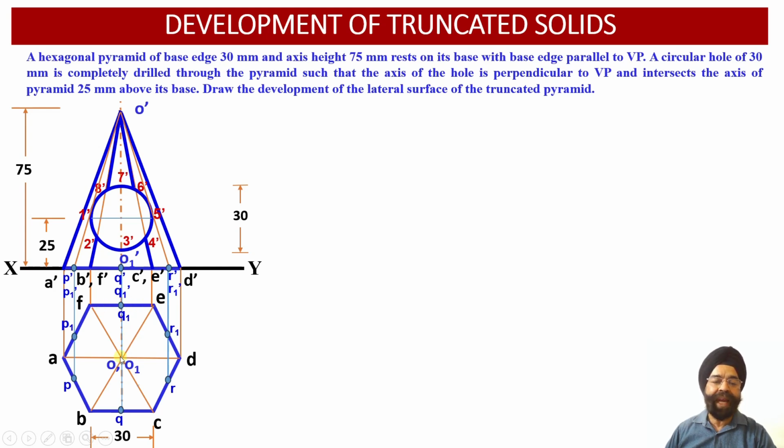So we are going to assume that this slant edge will be lying onto this triangular face OEF over here. Similarly, OQ slant generator, this will be obtained onto this slant surface OBC, which is again an inclined surface over here. So this way 2 points which are symmetrically obtained diametrically, they will be obtained onto the generators OQ and OQ1. So now you can check 4 points of intersections, they were available using the 4 slant generators which are already available over here.